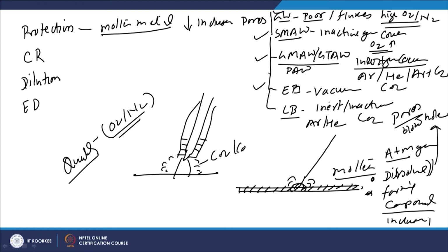Especially, the cleanest weld will be produced by the vacuum based processes, then maybe the GTAW process also results in a very low level of oxygen and nitrogen content. If we have very few impurities and gases, then the chances for inclusions, porosity, etc. will be reduced, and that in turn will help to increase the performance of the bead-on-plate surfacing. Now, the cooling rate is another aspect. The cooling rate affects the solidification time.